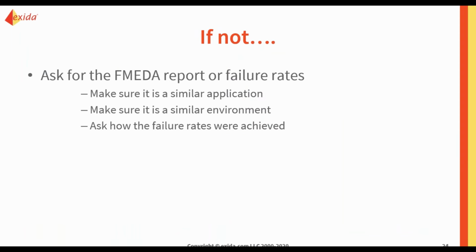What happens if you don't have a certificate or you don't find a certificate? Then go back and ask for a FMEDA report or the failure rates. Whoever you're buying your products from should be able to give this, especially if it's a certified product. If you're just given a FMEDA report or failure rates, even if you're just given a certificate, I always say, take the moment and make sure it's right for your application, right for your environment, and ask how those failure rates were achieved.